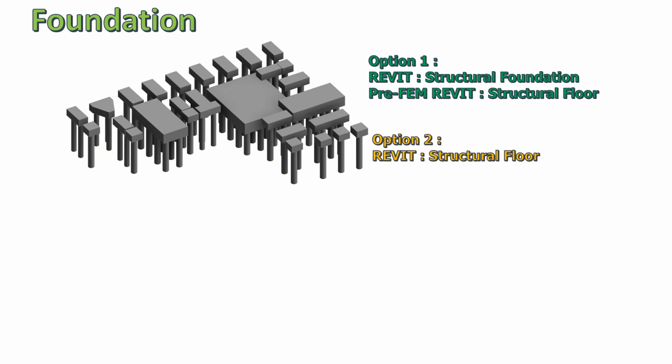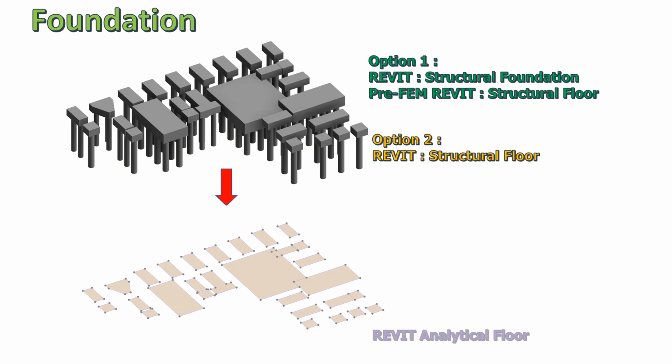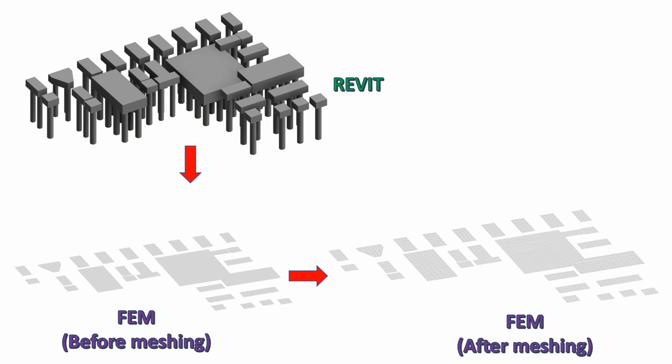Option 2 is modeling the foundation using the structural floor in Revit right away. The process of transitioning the foundation in Revit into the finite element model is now identical to how you do with the structural floor.